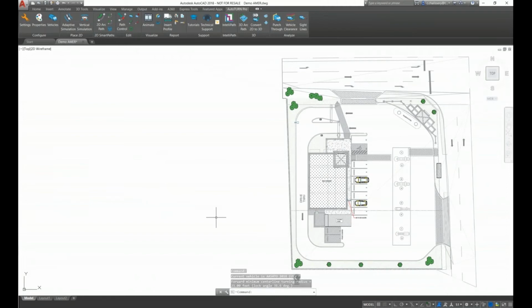Now that we have decided on the vehicle, let's select the relevant tool to perform this analysis. Unlike the gas station, the drive-through access around the building is a predefined path, and it's a single path. So the vehicle enters from here, goes through the drive-through, and exits from here. And also the vehicle moves at very low speeds through the path. Hence, considering all these scenarios, the most appropriate tool for this analysis would be the adaptive simulation tool.